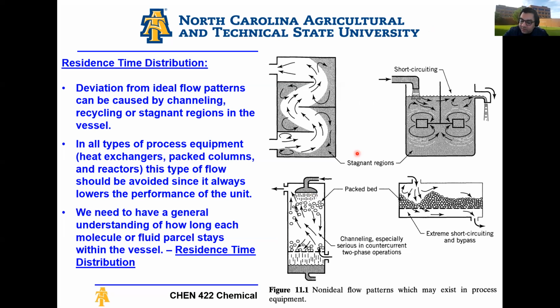and it's your job to try and determine, or try to control, the distribution of gas along the radius of the column and along the height of the column. And this channeling issue is a big deal, especially with distillation columns, even with absorbers, with strippers, with packed beds. You see this a lot.